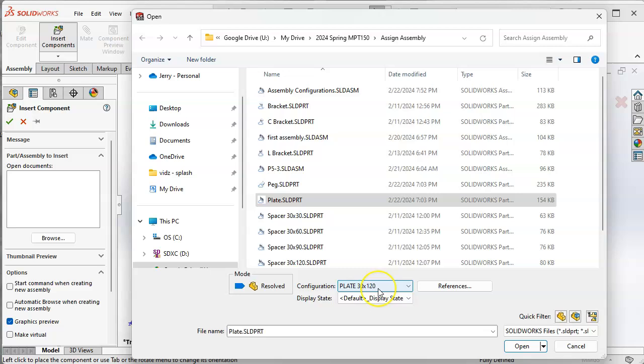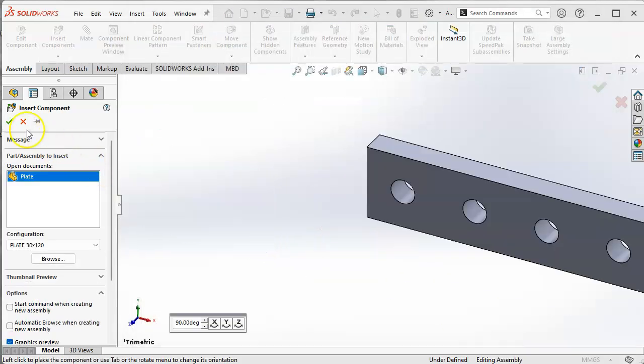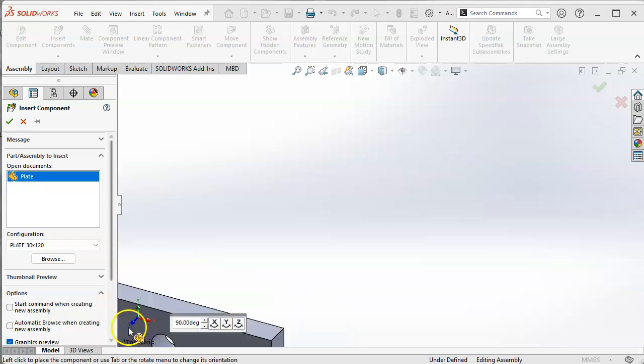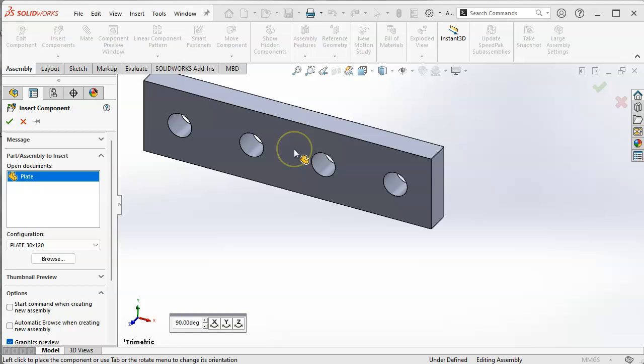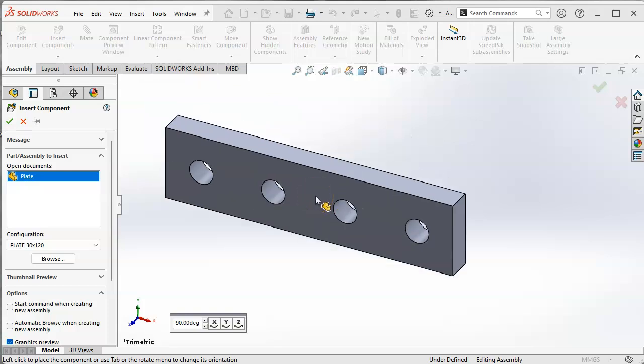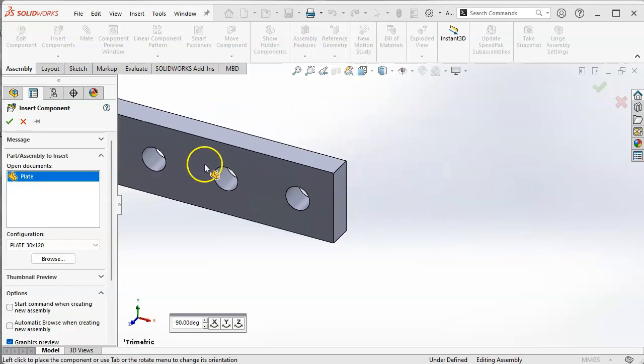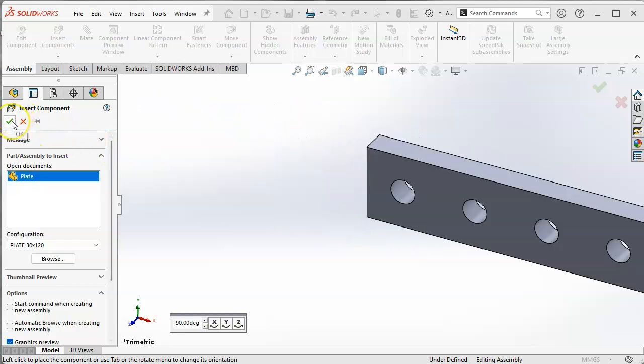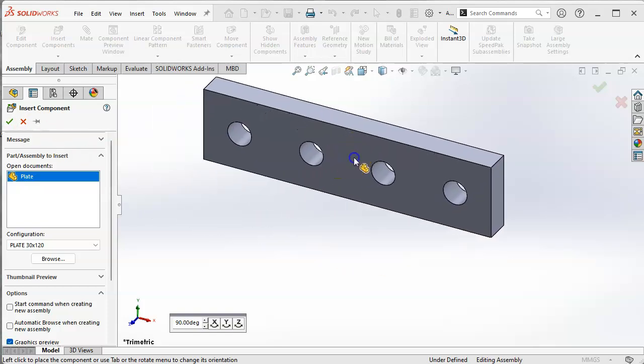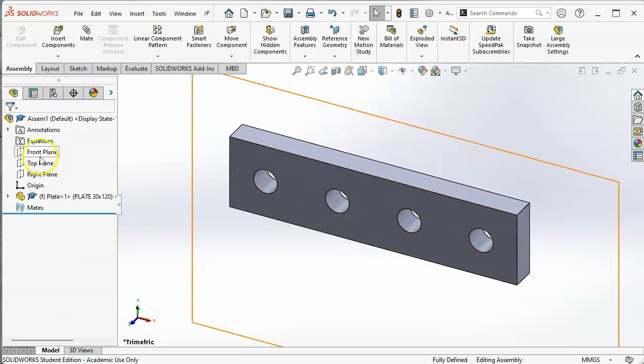So when I pick my 30 by 20, that's basically the quad, and we go ahead and position it. I also want to do the out of position. So if you recognize that you can rotate about X, we come down here to the end context, or we right click and rotate about X. But if I just bring it into position, notice the snap, it's done it a couple times. That would still be origin to origin. So I'm just going to click, and that puts it pretty much anywhere.